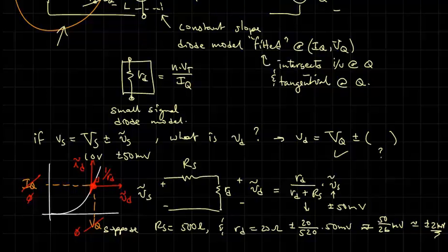In the end, the results that you need are, this is the model, it's a resistor. The value of the resistance is simply n times Vt divided by the operating current. n is a parameter of the diode. You're typically given that. It's the ideality or emission constant.